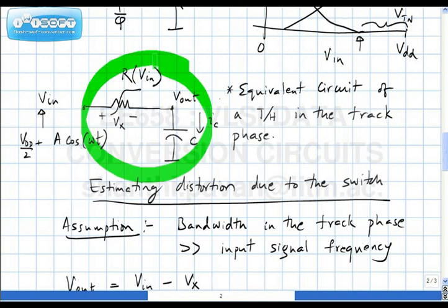And please note that in principle, a continuous time sine wave passed through a nonlinear network has all frequency components. But when you sample those frequency components, what happens? They will all alias back. So you will expect to see a whole bunch of tones.